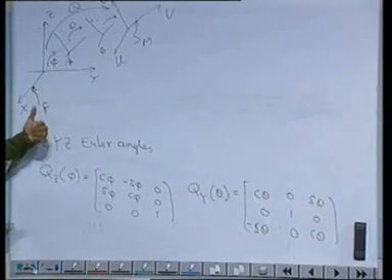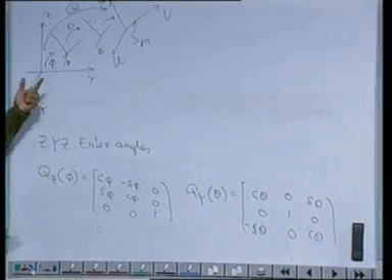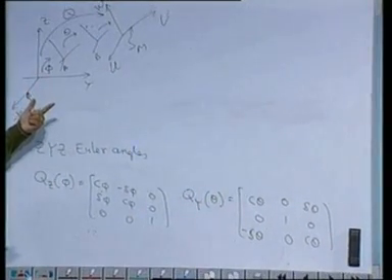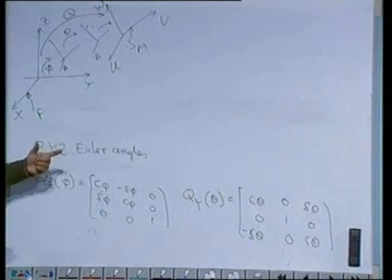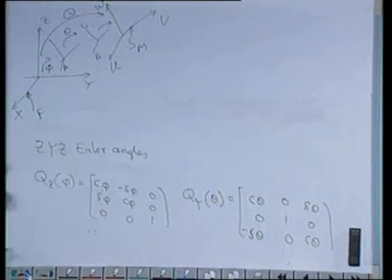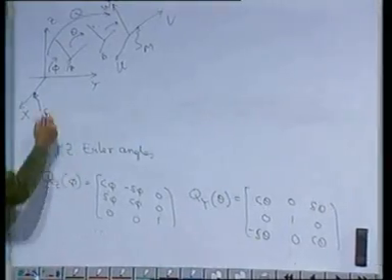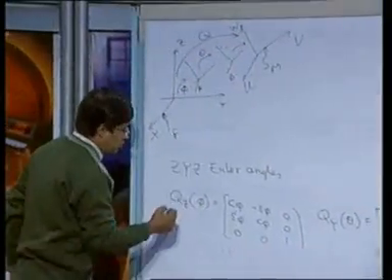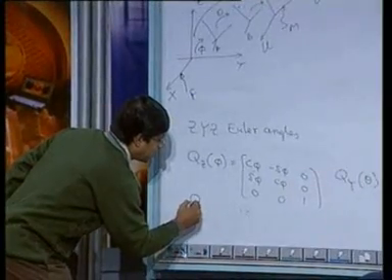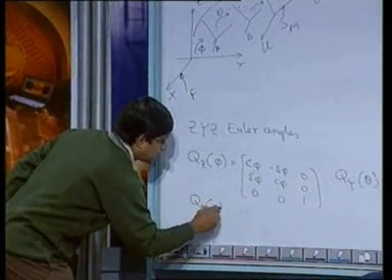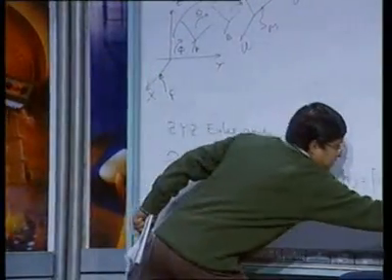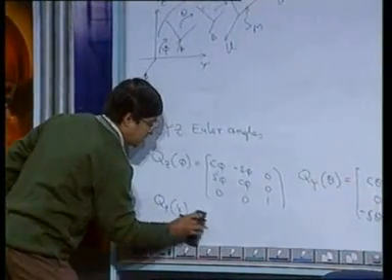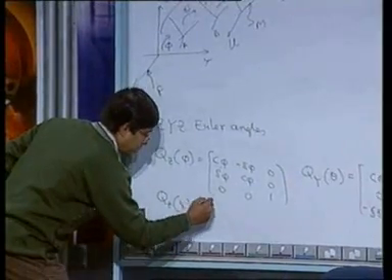We have derived the direction cosine matrix, knowing the coordinates in the moving coordinate frame represented in the fixed coordinate frame, rearranging the things and getting the matrix structure. You could try this one. Then, we reach B, and we give another rotation with respect to the z axis of the B frame, so that we reach the final frame.